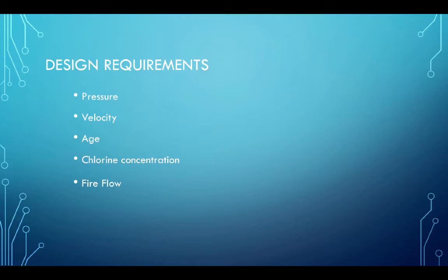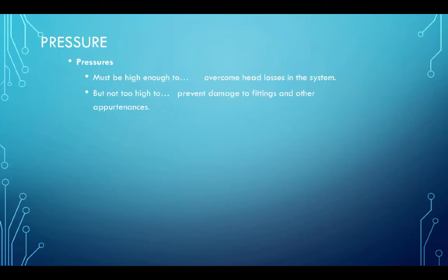The velocity is important because if the water is flowing too quickly in a pipe, it can damage the pipe. If the water has to be turned, the forces involved actually get substantial. So we're targeting locations to find where the velocity is perhaps unexpectedly high, and then we would engineer to accommodate that, either strengthen the physical structure to handle the forces involved or change the diameter to slow things down.